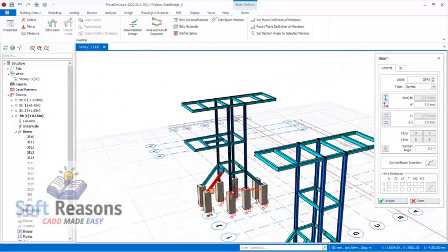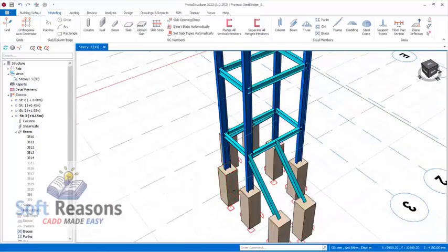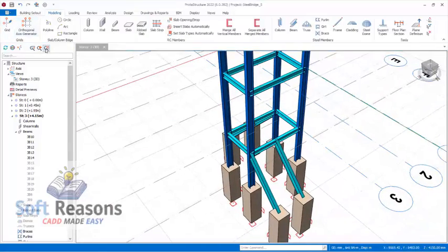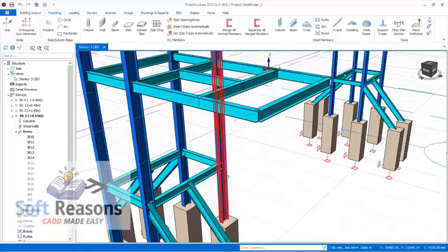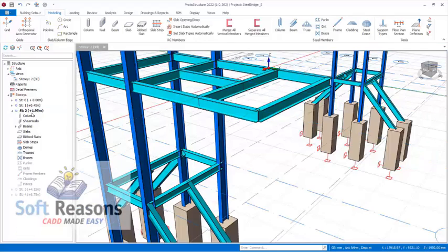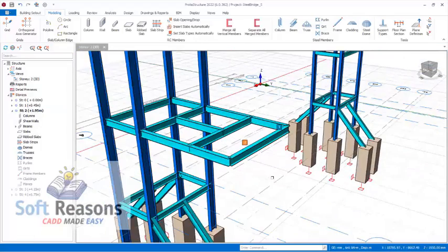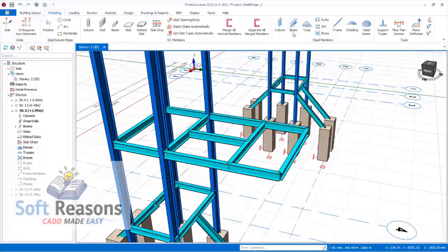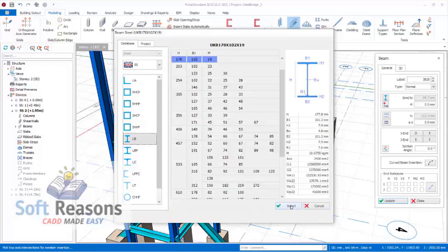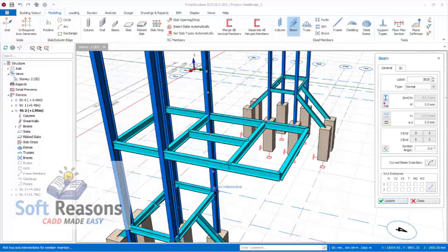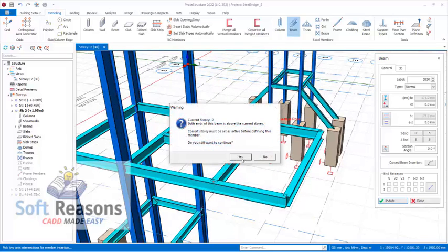It's not really giving us the exact point that you are supposed to place it, so you have to update this in a way that you can actually view it correctly. So let's navigate the green lines to the story 2 right there. At the story 2, get back to the beams, check the section is correct, select that, then pick it right there, take it all the way to this point, place that.